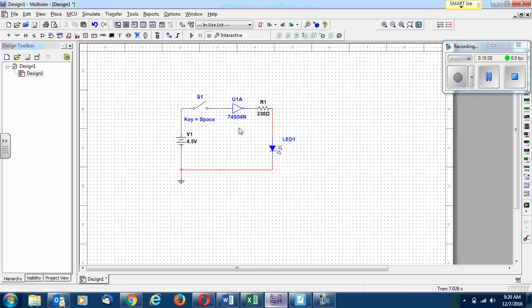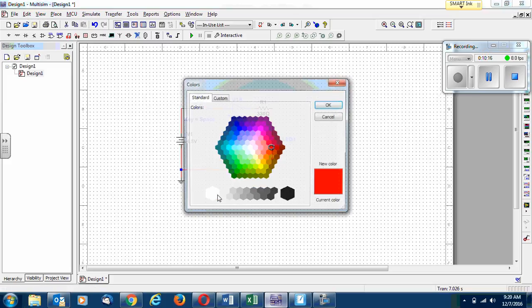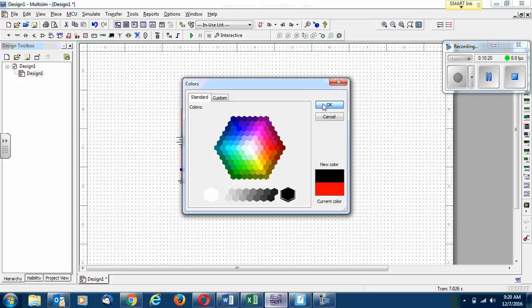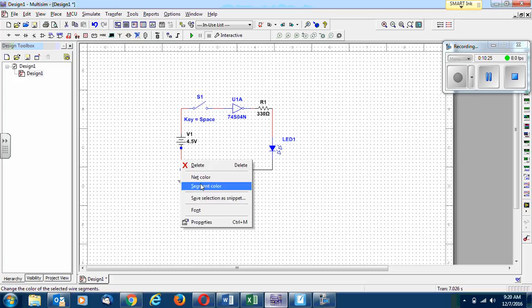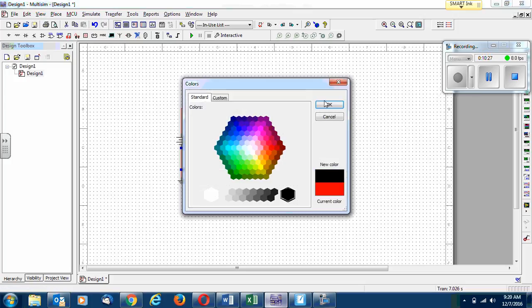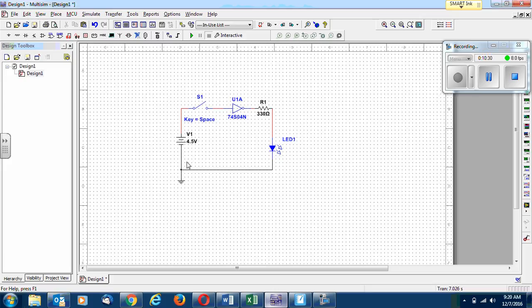Okay, well, the question is, do I actually have a low in my circuit? And yes, I do. That's the ground. The ground, guys, by definition is 0 volts. So I'm going to make it black. So everything that's colored in black right now, well, this one should go also black. But now everything that's black is 0 volts. Well, that sounds really good. That's way less than 0.8. So that should give me a nice 0. So my next idea would be to place a little wire over here.